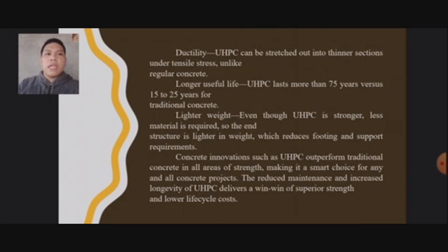And ductility: UHPC can be stretched out into thinner sections under tensile stress, unlike regular concrete. Longer useful life: UHPC lasts more than 75 years versus 15 to 25 years for traditional concrete. Lighter weight: even though UHPC is stronger, less material is required, so the end structure is lighter in weight, which reduces footing and support requirements.